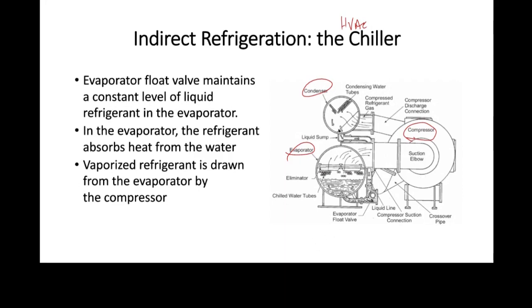And so what we have is liquid in the condenser, because what we've got is condenser water. So we've got the CW pumps pumping CW in and CW out. And it's cooler than the temperature of the refrigerant. So the refrigerant condenses and forms liquid, and the liquid goes through this pipe and builds up down here into a float. So there's the evaporator float. This is our metering device,